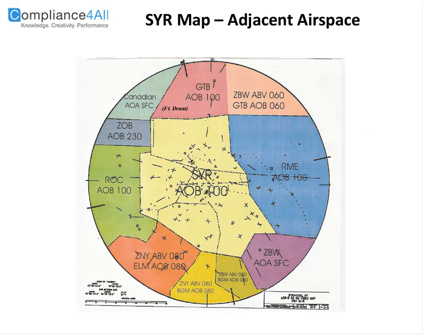So in addition to internal airspace for the TRACON, they also have adjacent facilities that they have to worry about, adjacent approach controls. This is Syracuse right here, off to the right, and Syracuse owns at or below 10,000 feet. Okay. Here's Rome approach control, and that also owns at or below 10,000 feet. Here's Rochester at or below 10,000 feet.